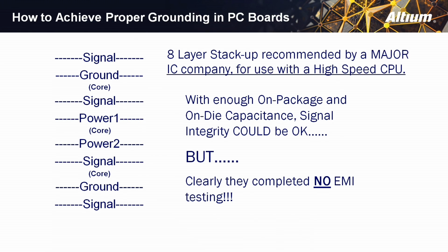Now, you could put a thick dielectric between power plane 1 and 2, and then power 1 would couple only to the ground plane on 2. And that's the good news. However, look what else is going on there. There's a signal layer between them, which means that in the dielectric space from where power comes, there will also be signal fields in that same space. They will couple to one another, and there will be EMI problems. This is what you absolutely do not want to do.